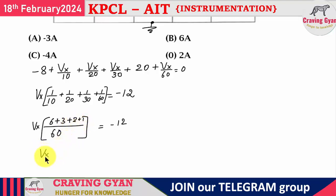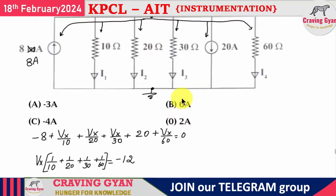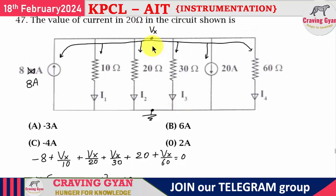So Vx into 12 divided by 60 equals minus 12. The value of Vx will be minus 60 volts. The node voltage is minus 60 volts, right? So this Vx is minus 60 volts. Here you have the ground potential, and the current is flowing from bottom to top.